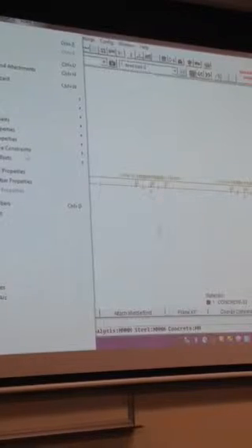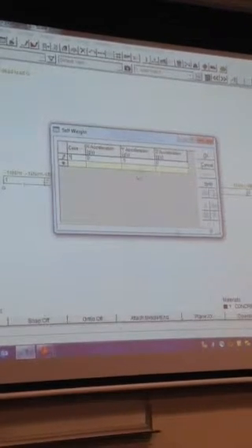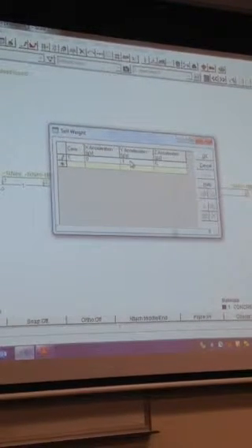There's one thing that's missing. Remember how I said that Space Gass you can input self-weight? And so we need to actually put in a gravity load now. So we can come down to, oops, wrong one, to loads, and one says self-weight. So we're going to load case 1, and it does it in terms of G's, in terms of acceleration.